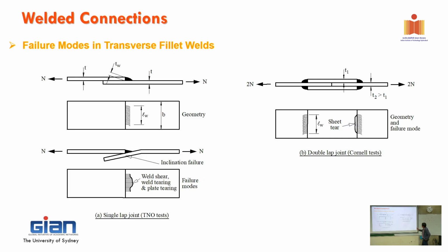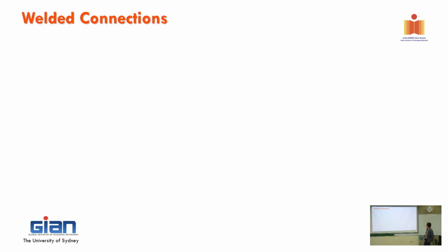Okay. So with thin wall or cold formed, normally you have single lap, and then this is popular as well. And sometimes if you want to make it concentric, you can bend it a little bit and weld like this one. Is it possible to do that? And you can weld it transversely or longitudinally. So that's different ways to do it.